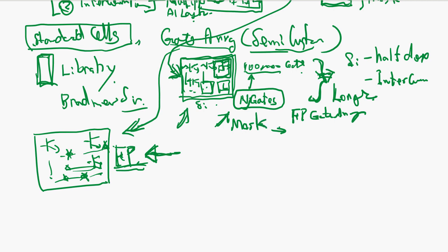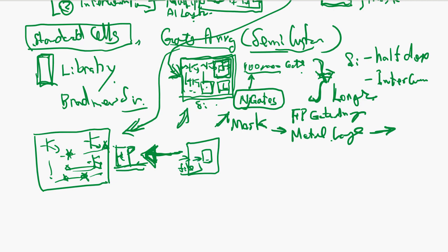The last portion, the metal layer process. This can be done at your desk, right? You have a field programmer, you put the chip on it, and you give the file, the logic file you want to create. Then 30 minutes later, it has cut all the fuses and the interconnection is done correctly. Then the chip is done. So it's a tremendous time saving and cost saving. Okay, so that's why this has become much more popular than the traditional gate array.